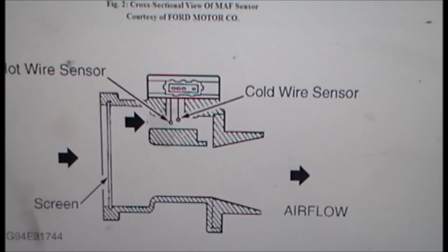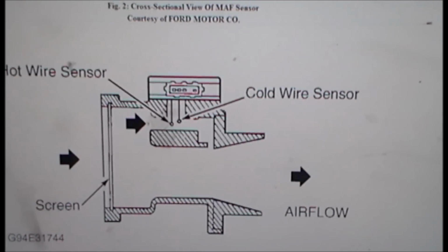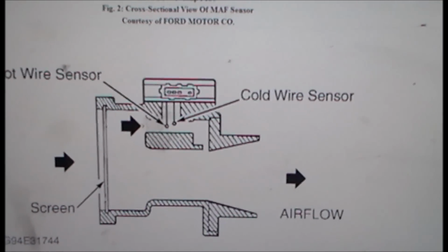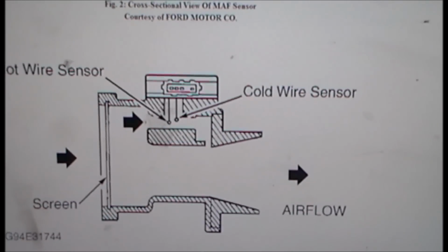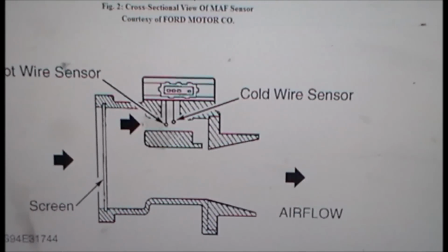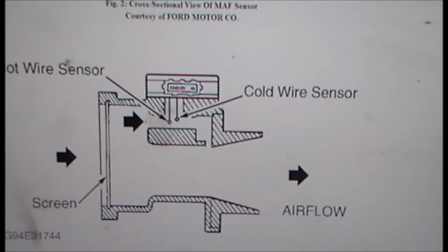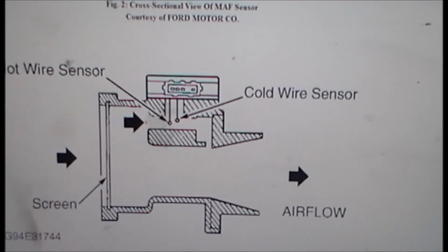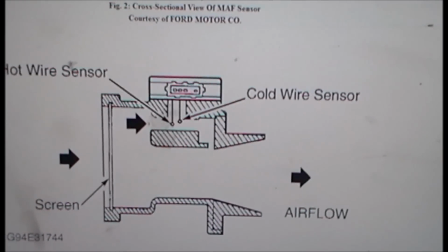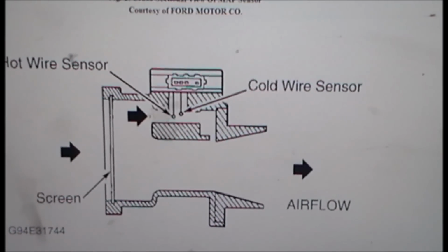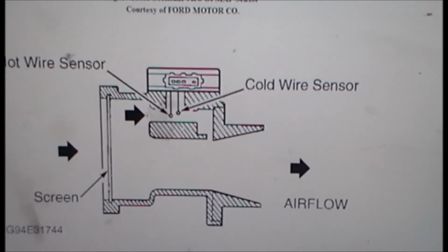So you've got two sensors inside that usually get packed full of dirt, and they're insulated, so it doesn't see the air coming across, doesn't cool it down enough, so it thinks that there's not as much flow going through. So you usually clean those off in this scenario, and you'll see a dramatic change on your scan data when you drive it.